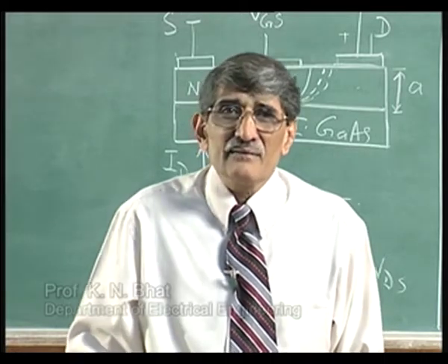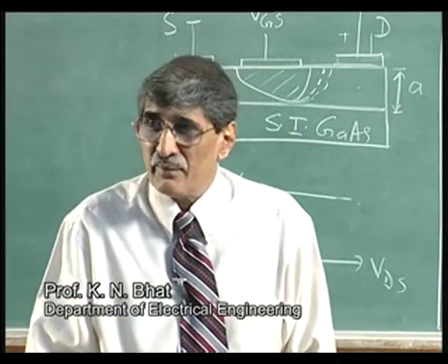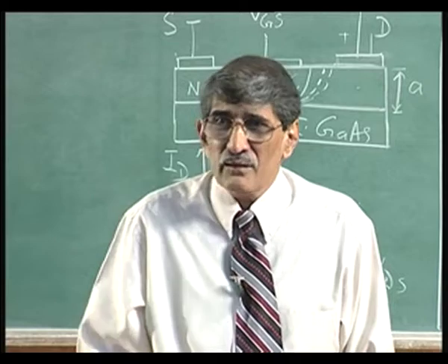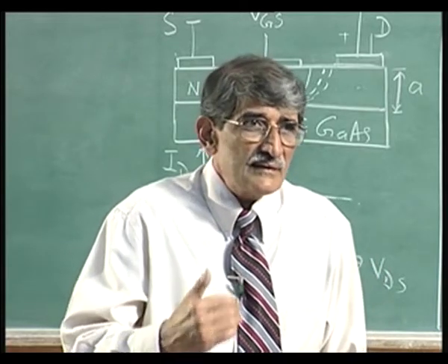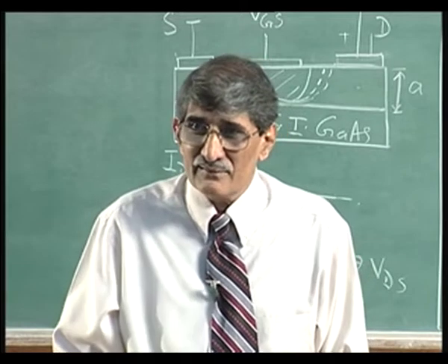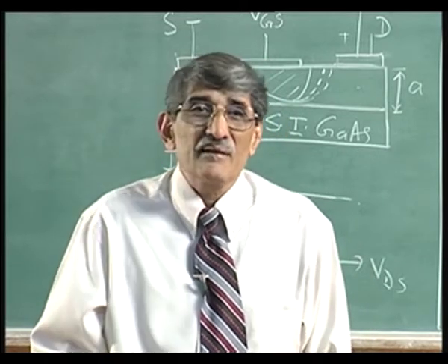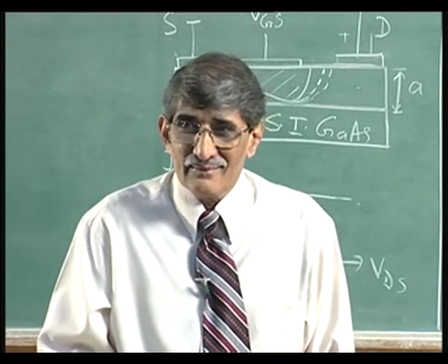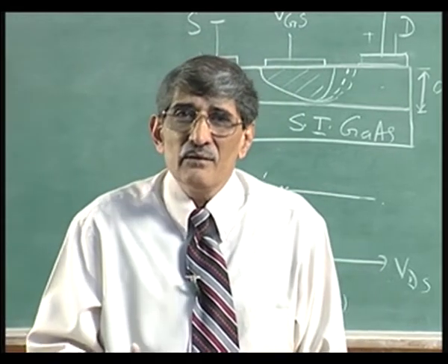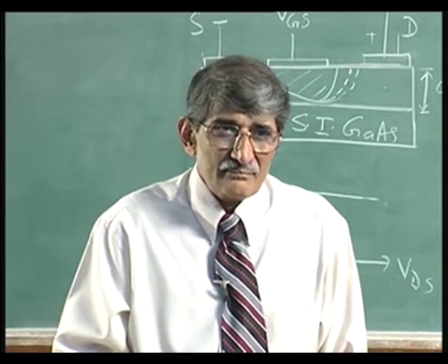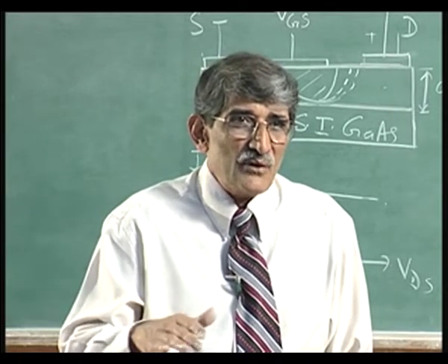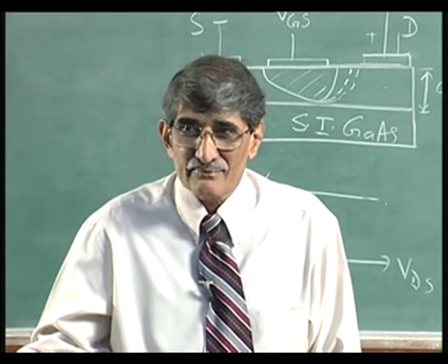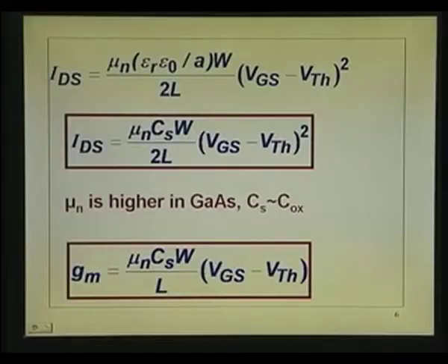Okay. In fact, I was just mentioning some other day some people in some of the companies in US who were coming here for a discussion. You are thinking of the MOSFET with thinner and thinner and thinner oxides. You remove the oxide, you get MESFET. That should give you better performance, because you talk of bulk mobility. It is easier said than done. There will be a lot of problems associated with that, but I am sure people are moving in that direction. Finally, remove the oxide. You do not have to worry about all those things. Okay? In fact, you can see the flavor of that when you discuss the gallium arsenide MESFET properties. One of the things is this: better transconductance, better speed.